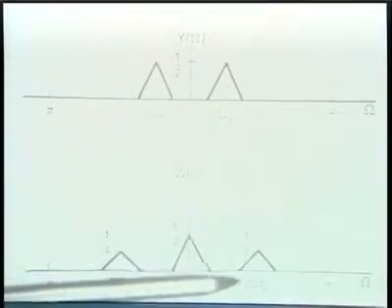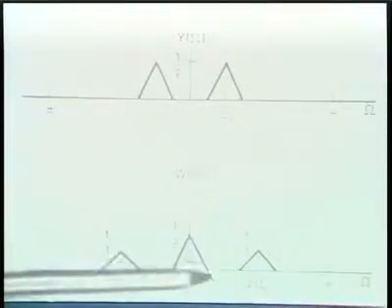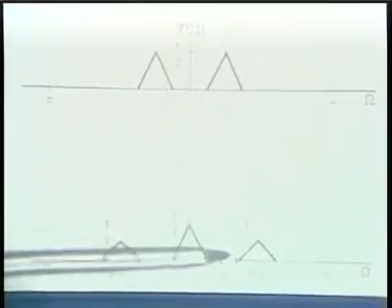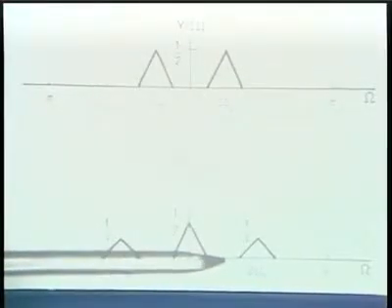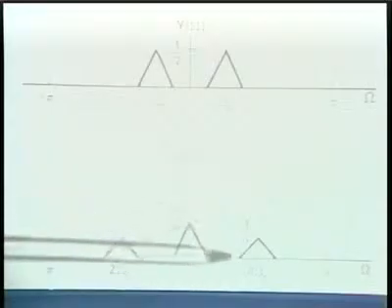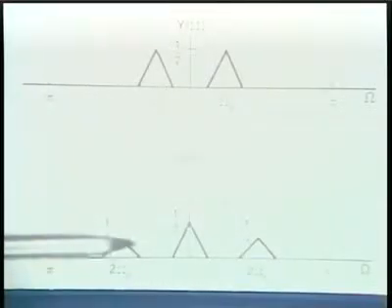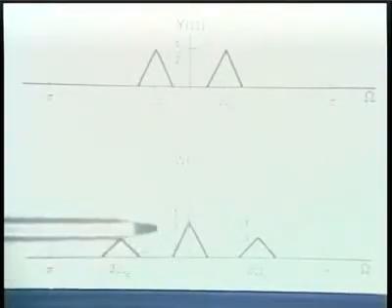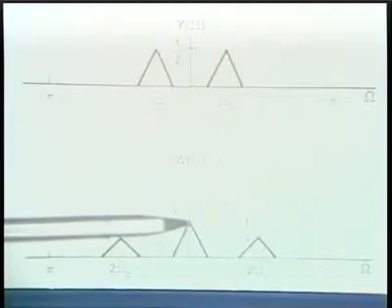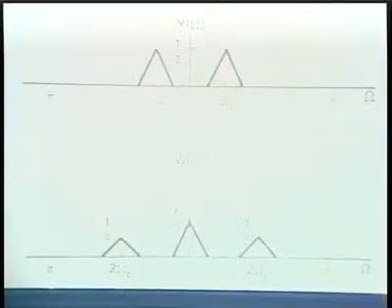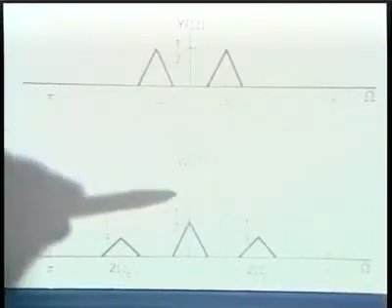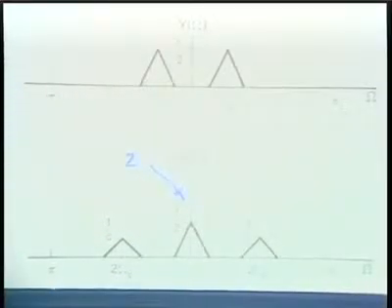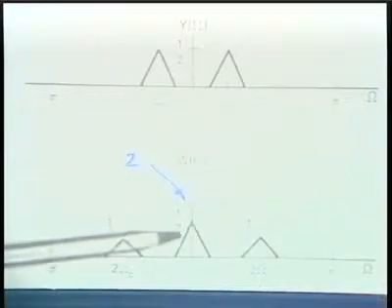And as long as the carrier frequency is large enough compared with the width of the original signal, then, as you can see, by extracting this part of the spectrum with a low-pass filter, we can, in principle, recover the spectrum associated with the original signal. And again, just as in continuous time, because this amplitude is a half, we would want to choose, for scaling purposes, a low-pass filter amplitude which is 2, to compensate for this factor of a half.